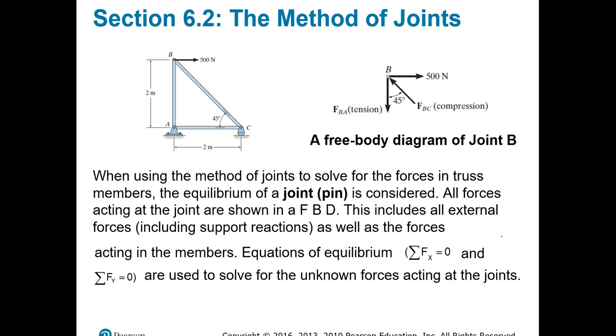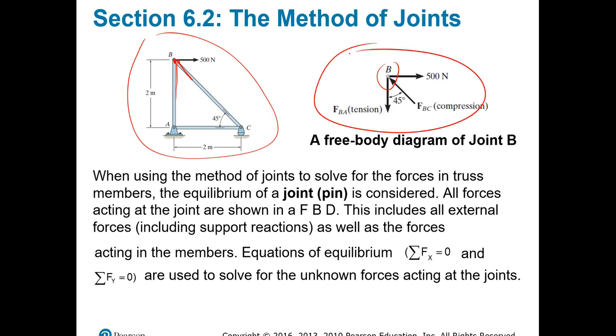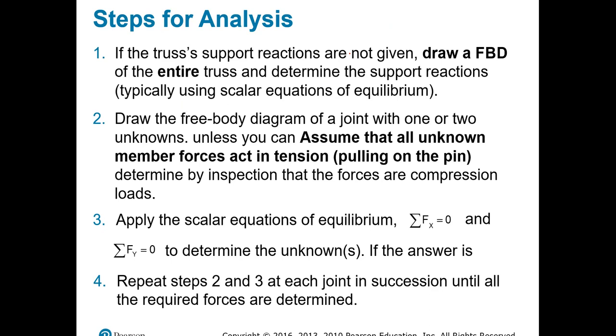What is very important right here, as you have the truss, is that we study the pins in which all the members are joined together. So AB goes to this pin right here, BC also goes to that pin, and then you have the force acting on it. And that's why studying those pins is what will give us the information that we need to design the trusses. And after that we need to apply the equations of equilibrium, which is sum of forces in the X direction, Y direction, and the moment, the ones that we know.